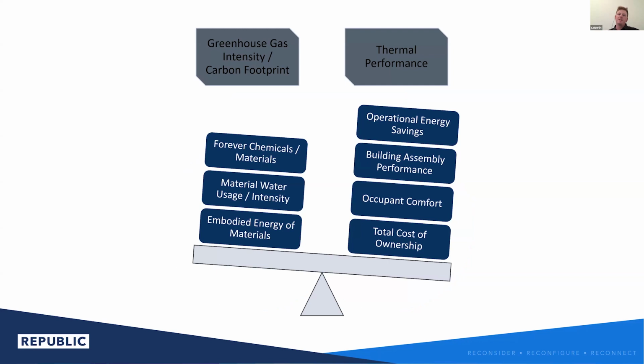I mean, this is something that kind of gets us into a weird bind where we find that sometimes adding more insulation is really just a net negative in terms of hitting other sustainability goals. Because sustainability, unfortunately, is not just thermal performance. We need to look at greenhouse gas intensity and carbon footprint. And I think this specific site in Edmonton that I was first discussing, we were seeing a very outsized impact on operational energy savings just because of how dirty the grid was there.